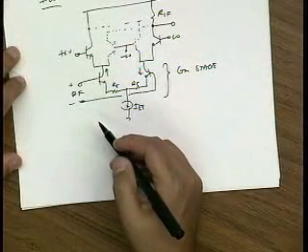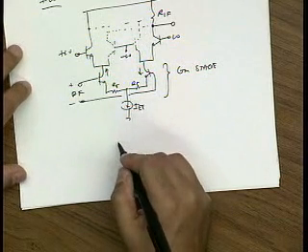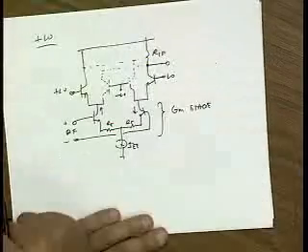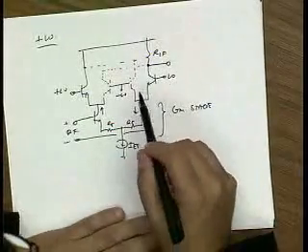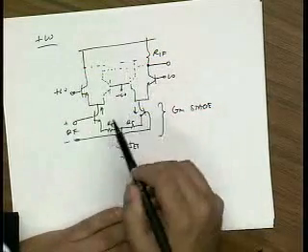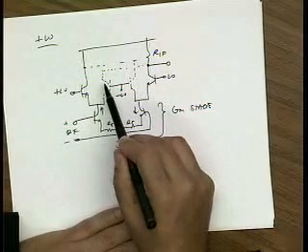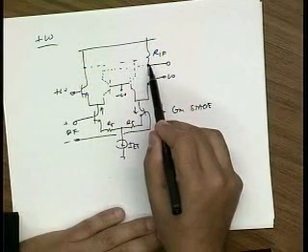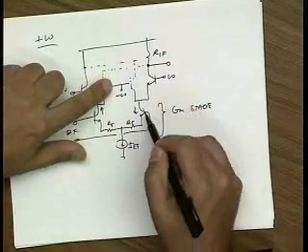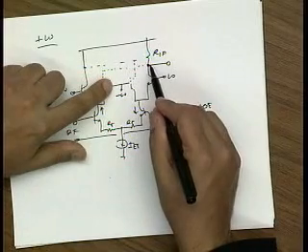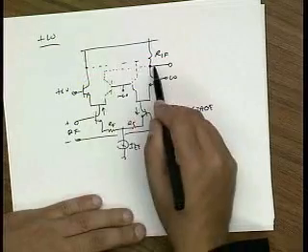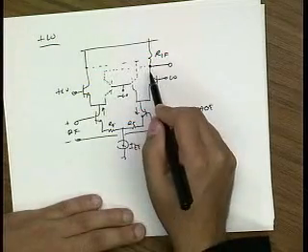Let me draw now also what happens during the negative LO cycle. Well, I guess I don't need to draw it. You guys can see what happens. So during the negative LO cycle, the current from this guy now is shunted to supply, but the current from here flows to this transistor and then flows to the output. So the interesting thing is that before, when we didn't have this transistor, the current would just get multiplied by 1 and then 0. Now the current gets multiplied by 1 and then -1 because this transistor feeds the output.